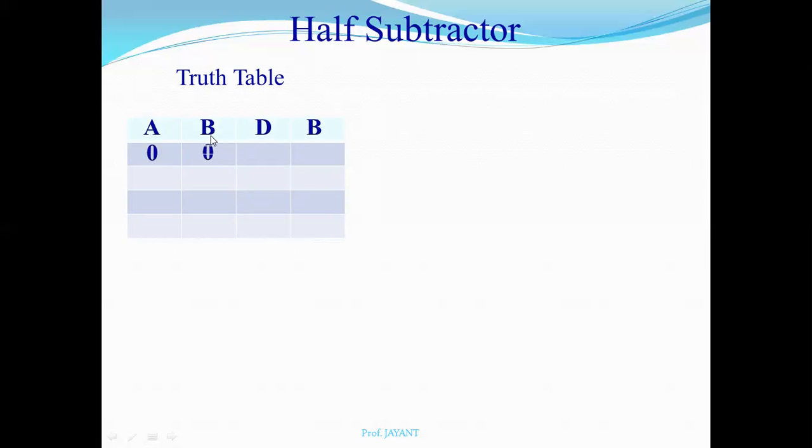So the combination of A and B is 0, 0: 0 minus 0, difference is 0 and borrow is 0. For 0, 1: 0 minus 1, difference is 1 and borrow is 1. For 1, 0: difference is 1 and borrow is 0. For 1, 1: 1 minus 1, difference 0 and borrow 0.